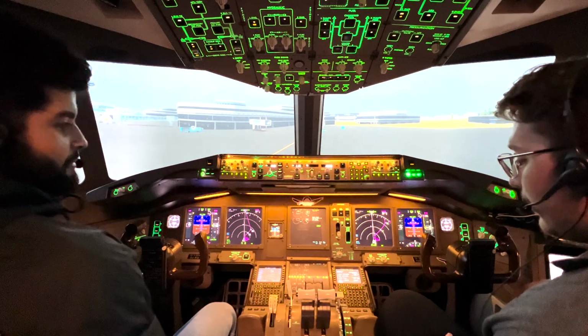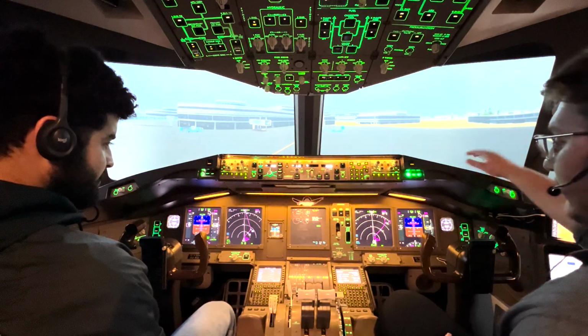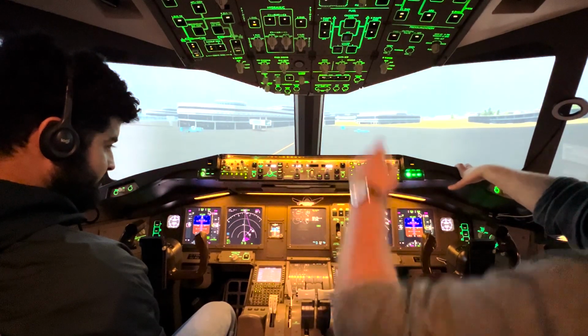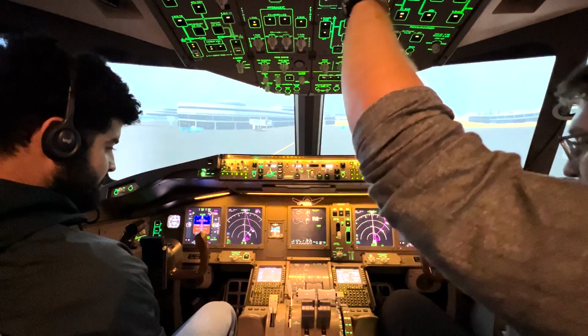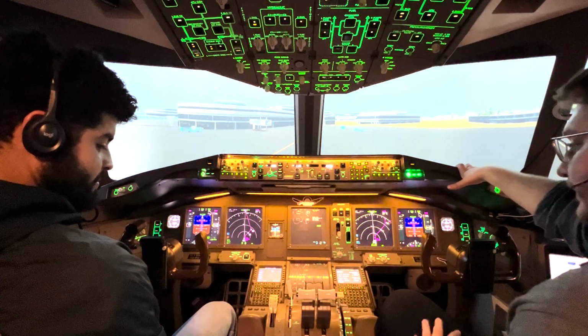So we're going to watch our oil pressure here. We got 31 psi, exhaust gas temperature is 250. Our N1 speed is 16, so that's about to click off. We're going to watch the switch here. Watch, it just went back to normal. So engine number 2 is started. We'll start up engine number 1 now, and we'll go ahead and introduce fuel.